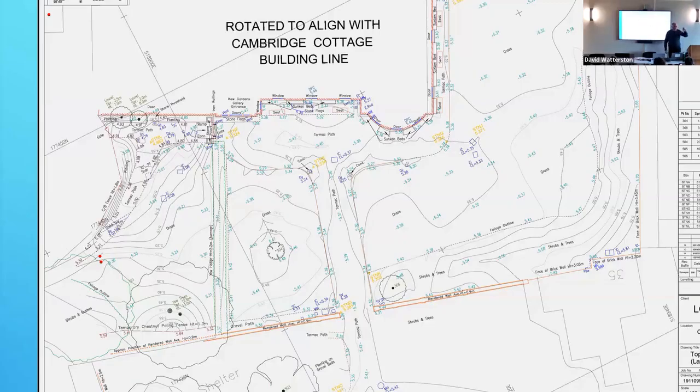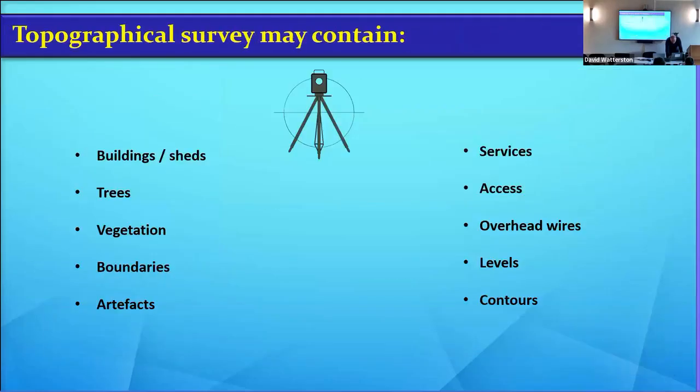And that's the Ordnance Survey origin. So where the origin was, I don't think it's Newland, but it's probably way down that way. So you can measure from that grid line to that and say it's 518900, whatever, how many meters it is from there to that IC. So that's what the term, surveyor's terminology, is a grid. What grid do you want? But what you're talking about is a level grid. And the level grid is different because the level grid is the spacings between levels.